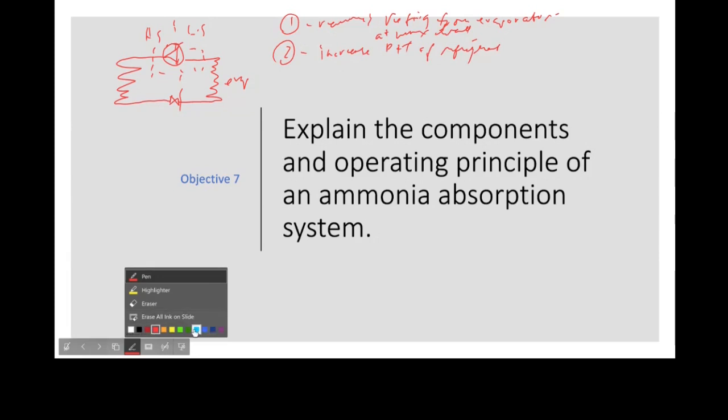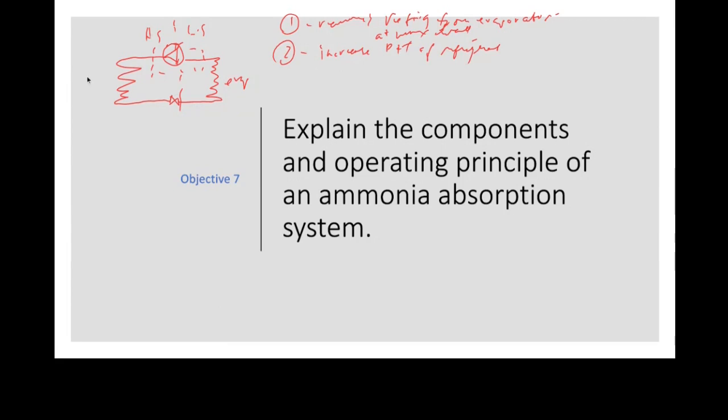Well, we've got a particular condensing medium. So this is our condenser here, and let's say we've got air going through at 20 degrees Celsius, with a fan over here, and the fan blows air through the condenser, which means that the temperature inside the condenser must be greater than 20 degrees Celsius. As a matter of fact, we saw that it could be easily 100 degrees Celsius or so.